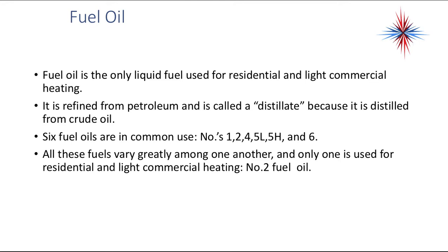It's refined from petroleum and it's called a distillate because it's distilled from crude oil. There are 6 fuel oils in common use. You have number 1, 2, 4, 5L, 5H, and 6. All of these fuels vary greatly among one another, but only one is used for residential and light commercial heating, and that's basically number 2 fuel oil.